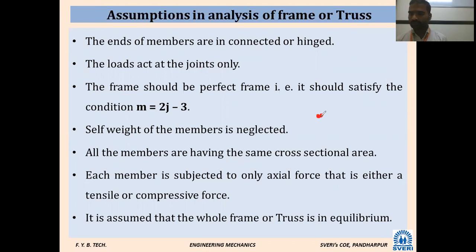So what is this one? This is a joint, correct? Yes. If the force is coming towards the joint, that is called compressive force. If the force is going away from the joint, that is called tensile force. These 2 points you have to remember throughout the chapter, because always if it is minus, it is compression; if it is plus, it is tension. That is, if it is towards the joint, then that is compression. If it is going away from the joint, then that is tension.